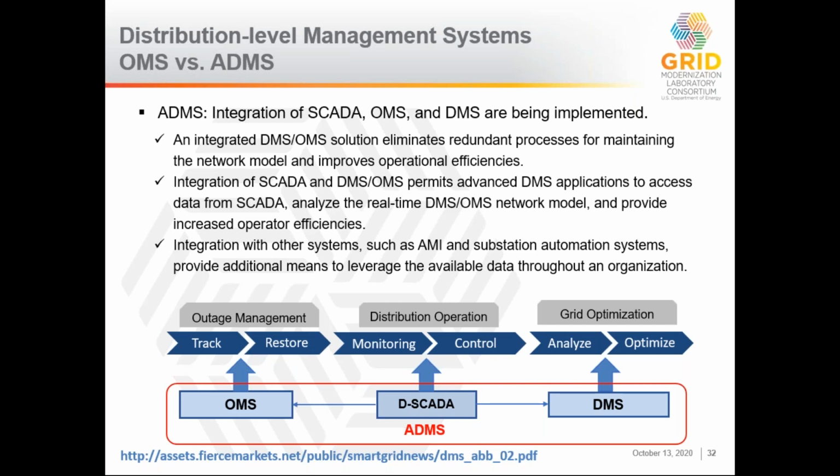It also improves efficiencies in how people communicate and manage different parts of the system. If we integrate SCADA and different measurement systems into this, it also helps get to more advanced applications for things like voltage management and some of the new distributed resource management systems that you might be hearing about as well. They're trying to integrate in various ways with the AMI networks and substation automation, but this isn't generally the normal state for most distribution utilities at the moment. It's a good direction that things are going, but there are obviously various technology roadblocks they're working through at the moment, around computation and cost and things like that as well. So next, sorry.